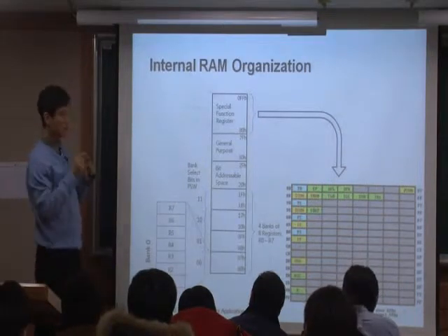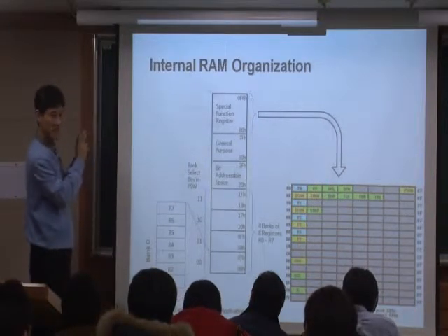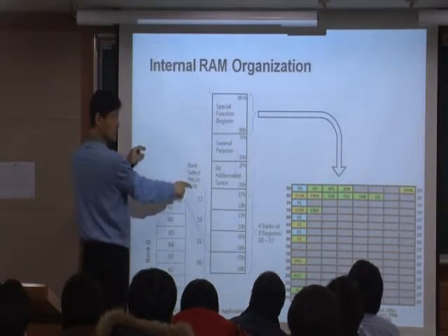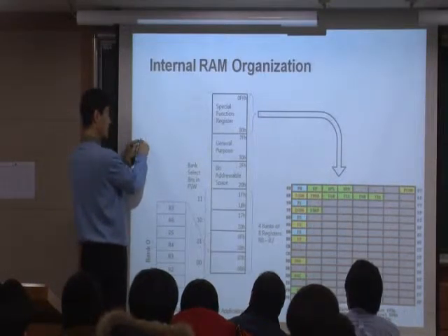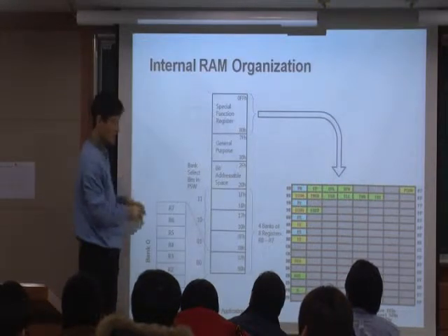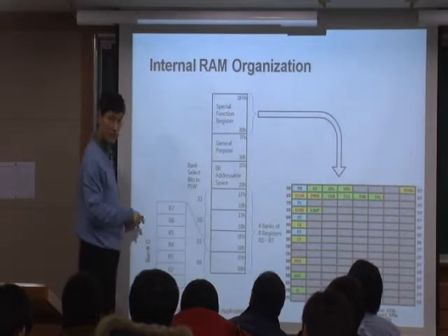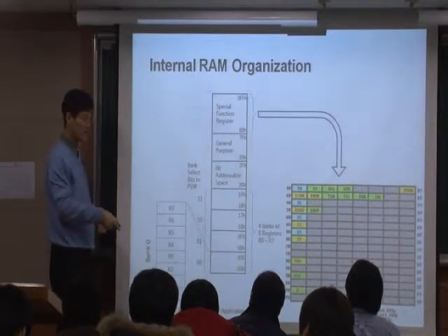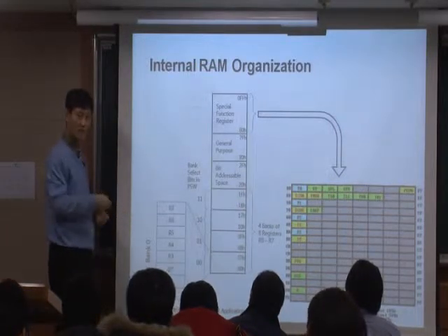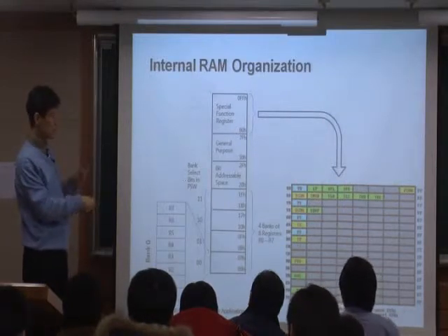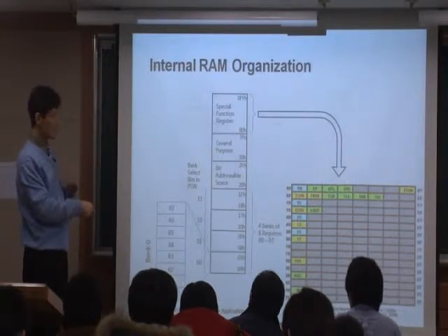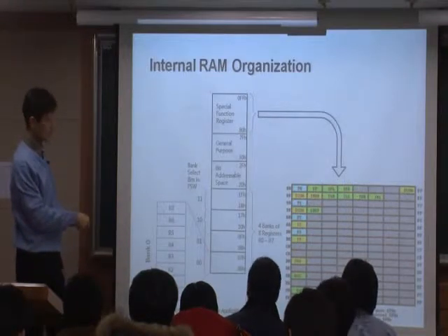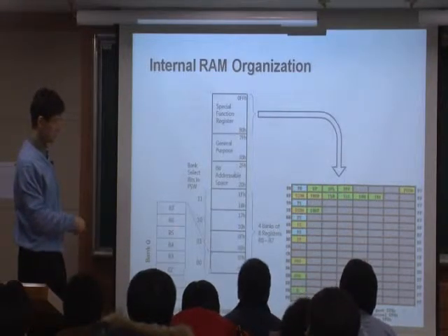So you first set those 2 bits. Like I say, in those 2 bits in PSW, I write a 0, 0. Then what that means is I want to select this one. If you write those 2 as a 1, 0, that means I'm going to use this bank. You're going to use those 2 bits to select your own bank. So you have 4 of them.